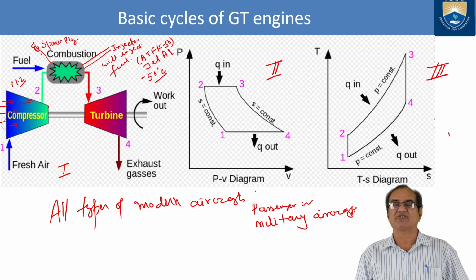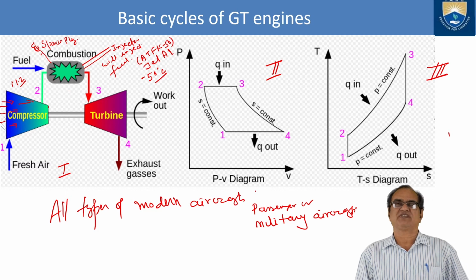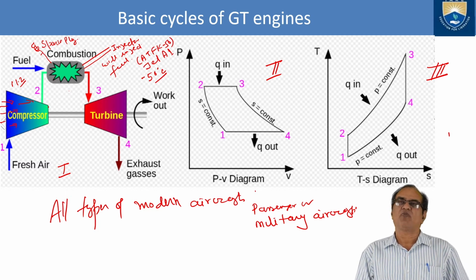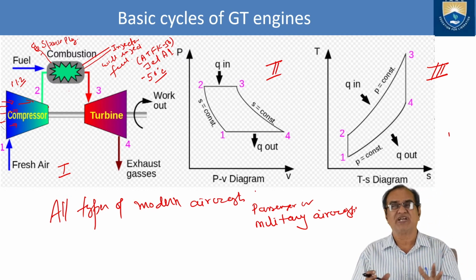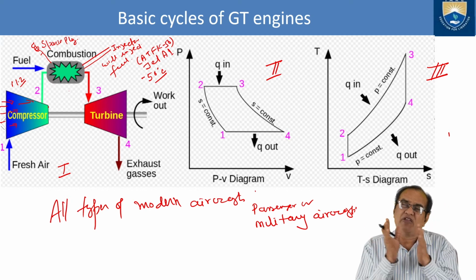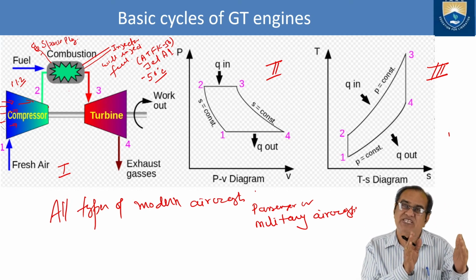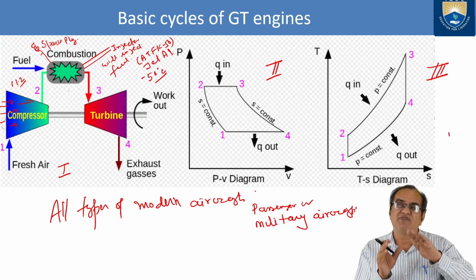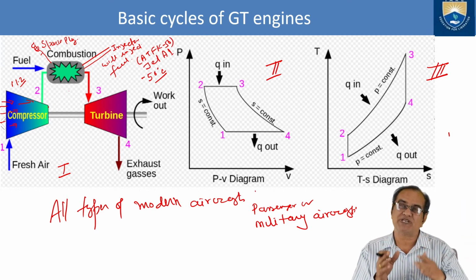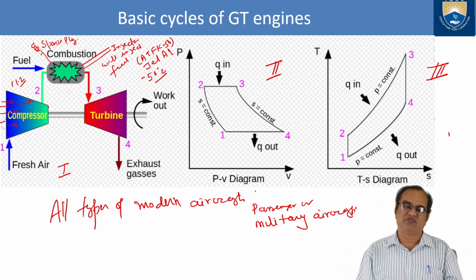They are methanol or some low freezing point additives, some 1%, 2%, as per the temperature. The more it goes into minus temperature, the higher the percentage. If it is going from minus 50 to minus 75 or minus 80, we use 1%. If it is minus 80 to 100, we will use 2%. From 100 to 150, we will use 3%. Like this, we increase the percentage of additive.